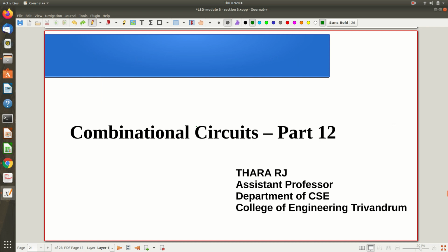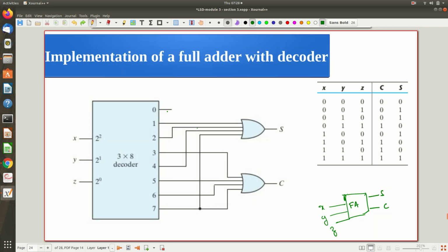So now you can go for the design of any combinational circuit, right? In this case it's very easy, because how can I implement the carry bit? We already have the expressions for the sum and carry. Hope you remember the sum is something like x XOR y XOR z, something we derived already. Using XOR gates, K-map and the simplification procedure, we come up with this.